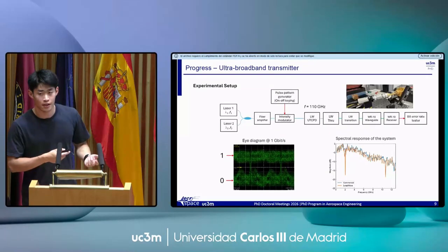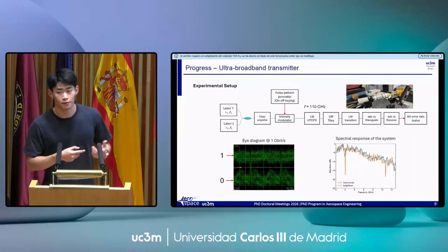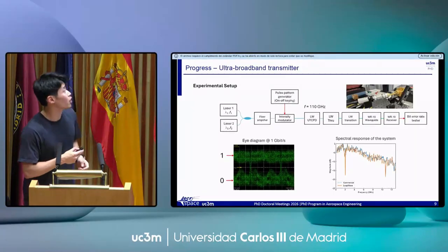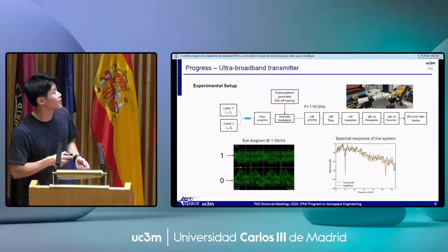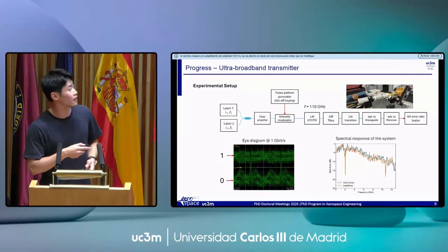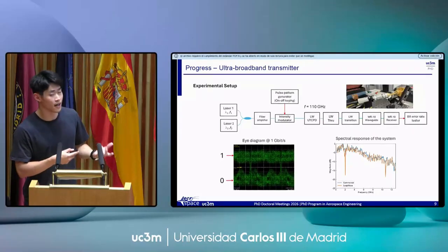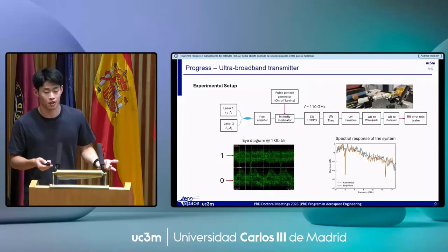We employed it in on-off keying communication systems. However, we faced a problem: we observed ringing in the eye diagram, even at a data rate of 1 gigabit per second. This ringing is caused by a low-frequency resonance inside the device, which basically destroys the communication.